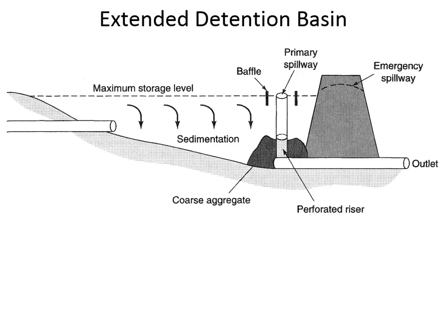Remember, v equals the square root of 2gh, where h is the distance from the water level to the center of the area of the orifice. And of course, because of energy losses, we put in a coefficient of discharge, C sub d, and we dealt with those in the labs last year.